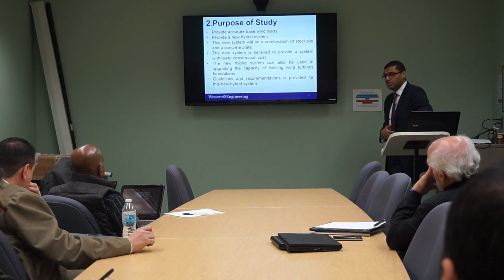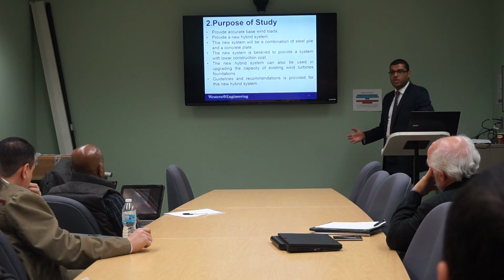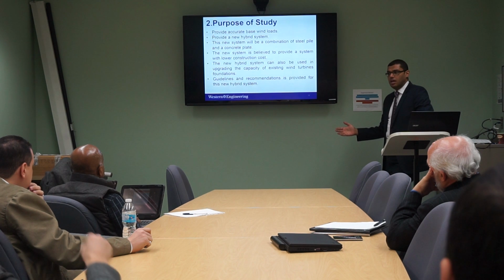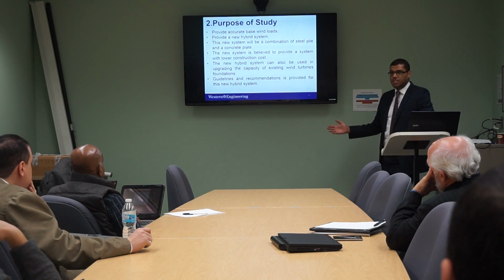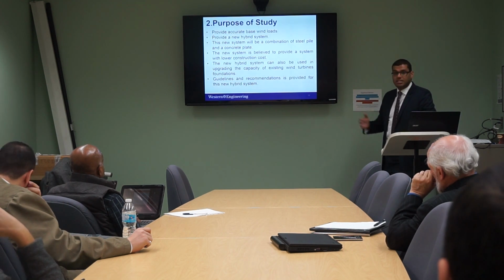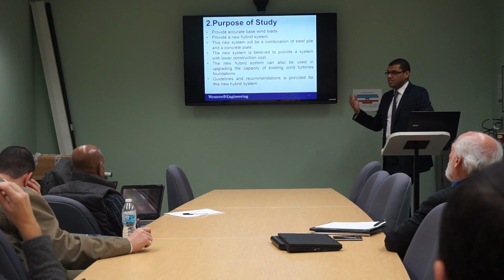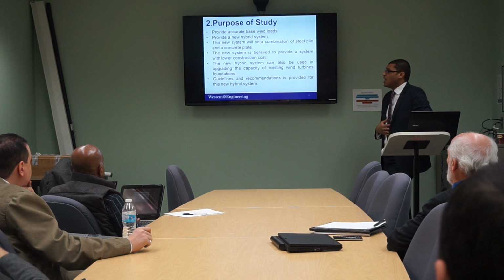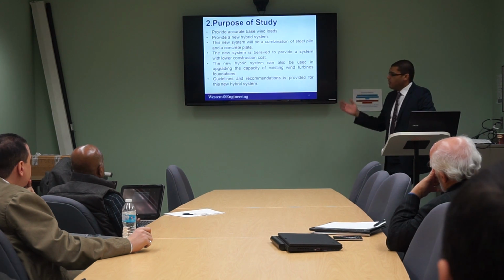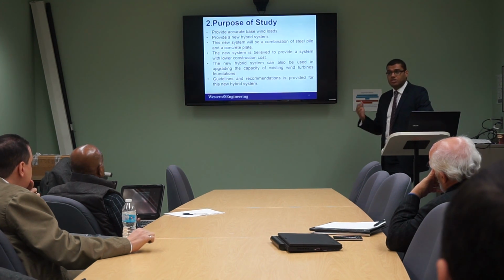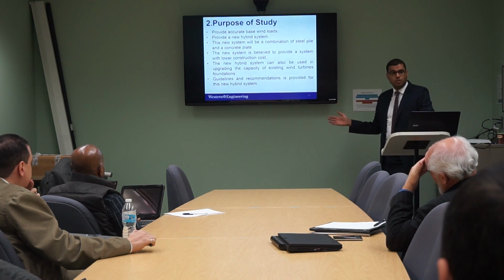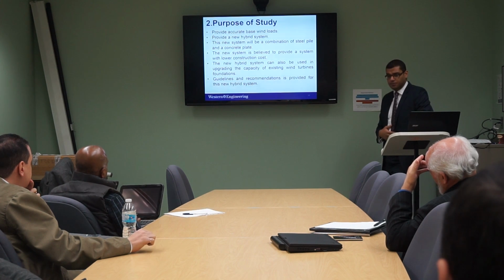This hybrid foundation system will be a combination of a steel monopile of 4 meters with a concrete plate to increase its stiffness. There will be a reduction in material, which can be a saving. This hybrid foundation system will also be able to increase the capacity of existing foundation systems. We have already provided guidelines and recommendations for this hybrid foundation system.